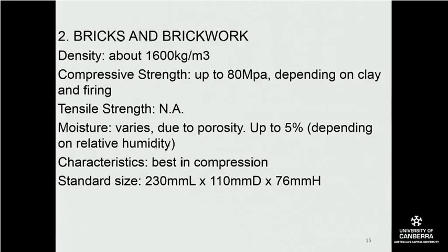Now, bricks, of course, can be made into many different shapes and sizes. In Australia, they are covered by 9 Australian standards to do with their manufacture, standard and quality control and what have you. But the standard size for brick in Australia is 230 millimeters long by 110 millimeters deep by 76 millimeters high. By and large, you're going to find that this is the standard size of a brick across the country.